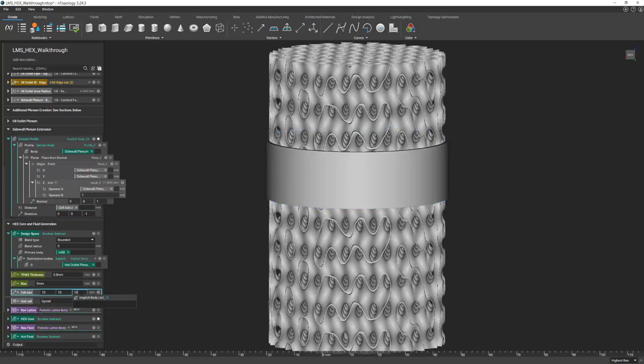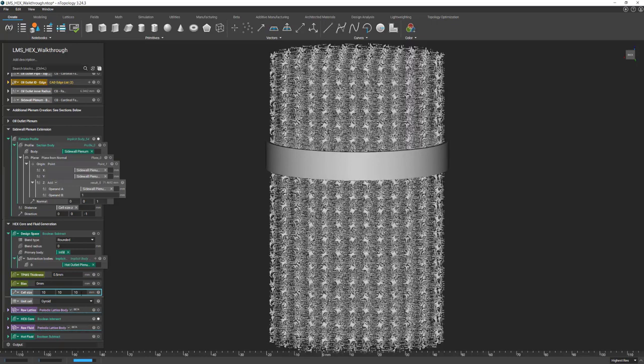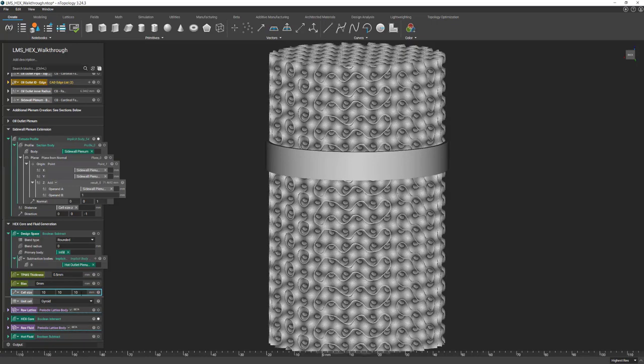And that extrusion comes straight down. So if we change this value to 10, it's going to move with the cell size. This will always just ensure that we are covered. So we'll make this a variable, and I'll call this sidewall extension.